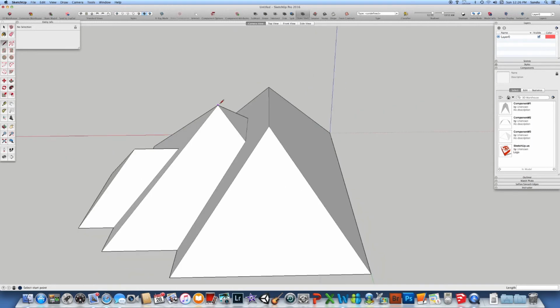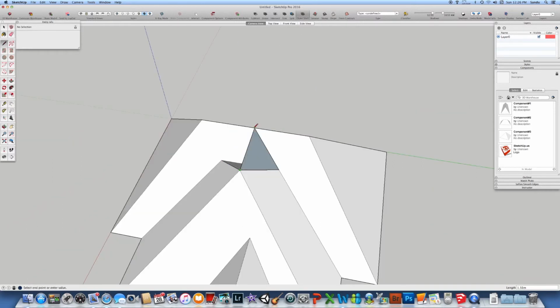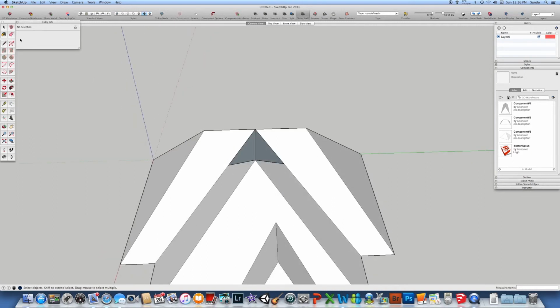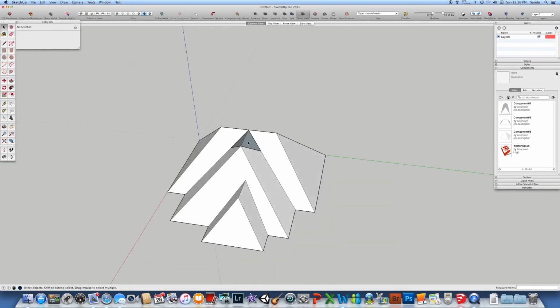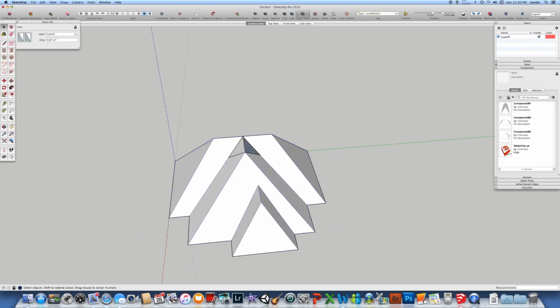So you need to make sure you have a line from here to here, and after that you create your two faces. Now notice that I'm not in the object, it is not in the component object. So if I want to add this inside, I can just reverse the faces again. But if I want to add it inside of this component, I will just need to right click and you click reverse faces. That is okay, this one is not okay.